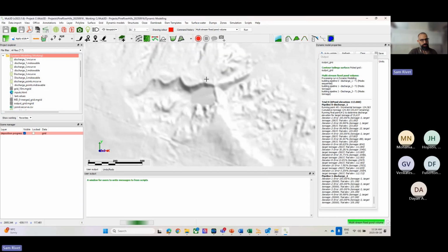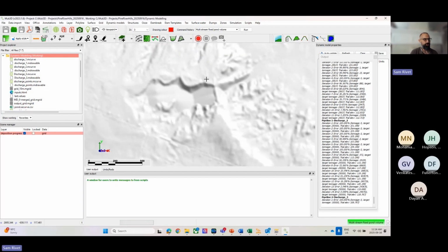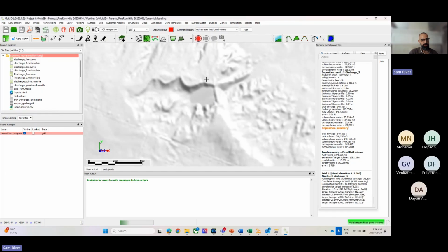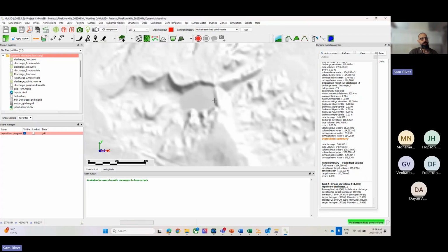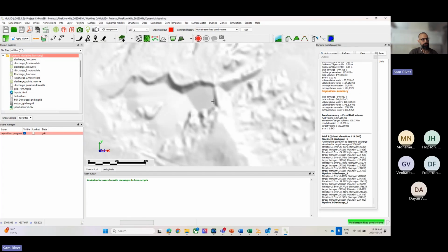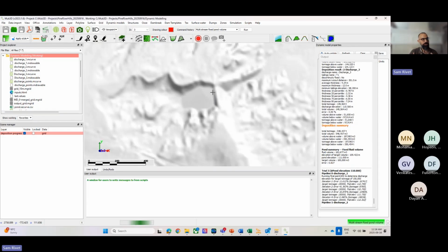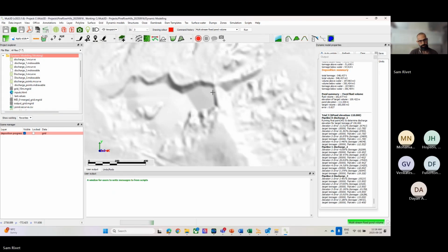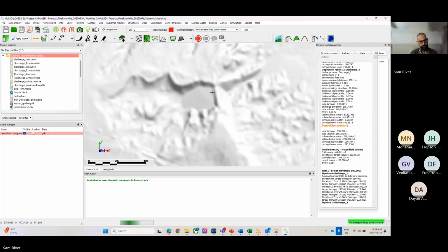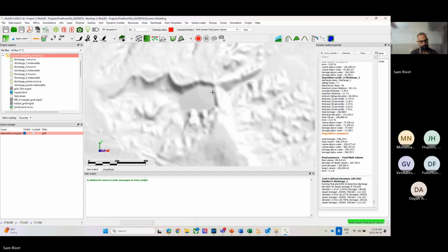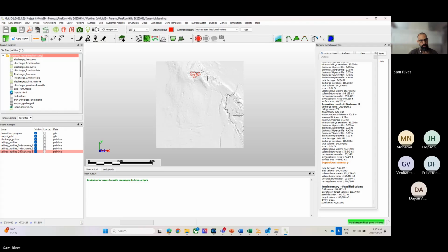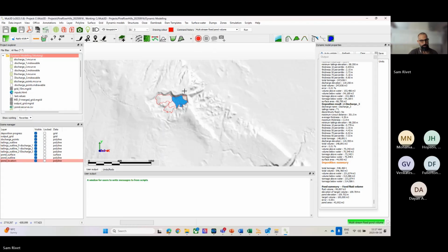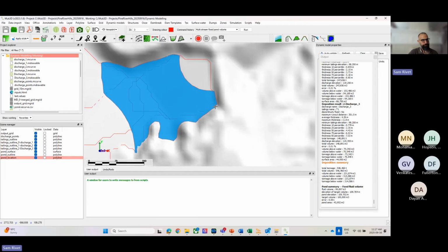So the big difference between sequential versus as drawn or flow path down slope is that it's going to deposit from one pour location and then from the other, as opposed to doing both simultaneously. So it can change the configuration of your beach. All right, we can see that here.